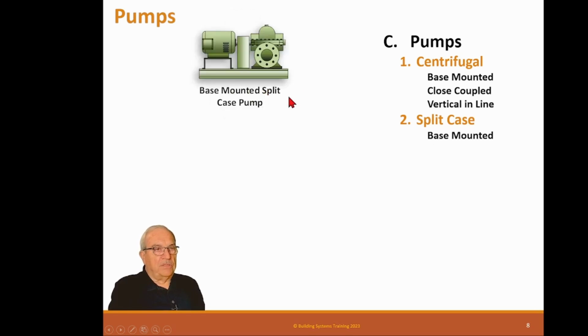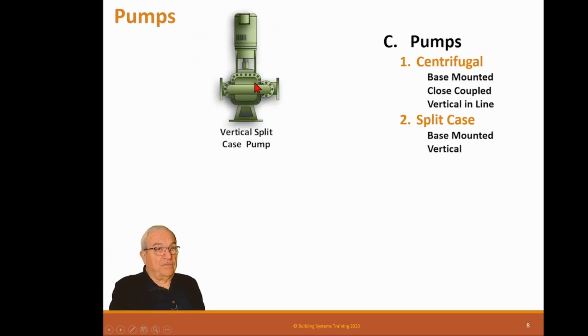Now I should mention on these, the impellers actually split. The water coming into this pump has an inlet on each side. It's like a double inlet fan. It's got double inlets for the water, and then the impeller pushes out this one exit. That's why it moves a whole bunch of water, because it's got two inlets. It's much easier to inlet than an end suction centrifugal.